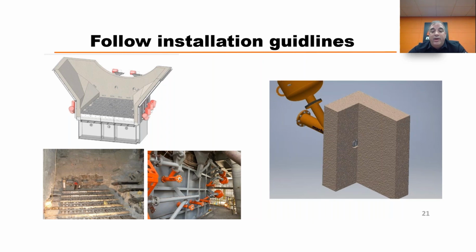If you're shooting out into the middle of the tower as opposed to cleaning the wall, that photo on the right-hand side is a nozzle embedded in the wall, and we're cleaning the adjacent wall surface. If I mount that nozzle half a meter out onto the wall, it's not going to clean the adjacent wall, and you've basically wasted it. Same with the angle. If the angle is off and I'm shooting out towards the center, your cannon is pretty much useless.